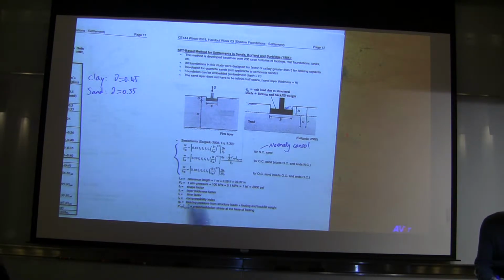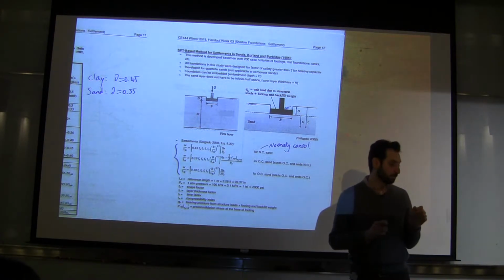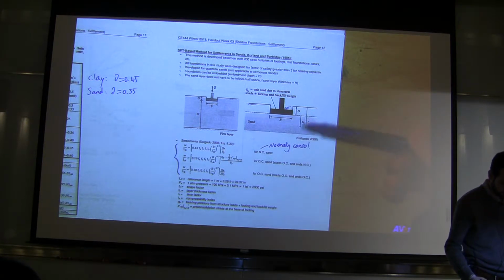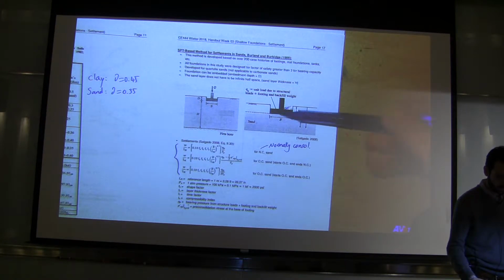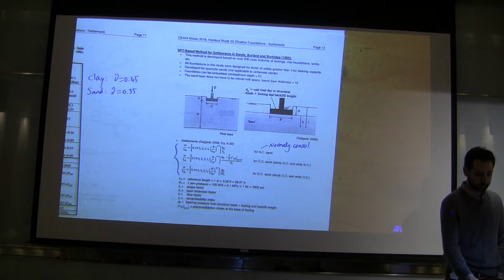And then for this case here, you see we have that parameter right there, sigma prime Vp at Zf equal to 0, and that's defined here. That's the pre-consolidation stress at the base of the footing. So before you add the footing, the pre-consolidation stress at that elevation. And that elevation refers to Zf equal to 0. That's Zf right there. So basically, that dashed line is what we are talking about.